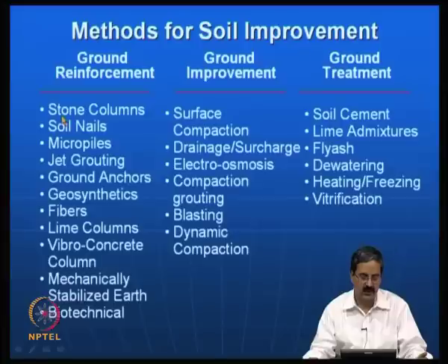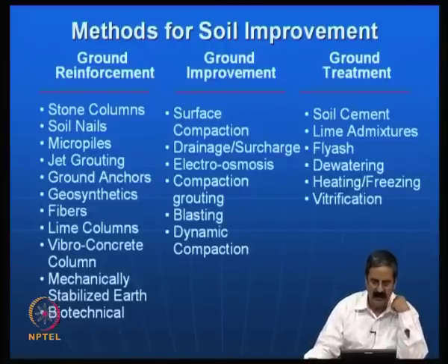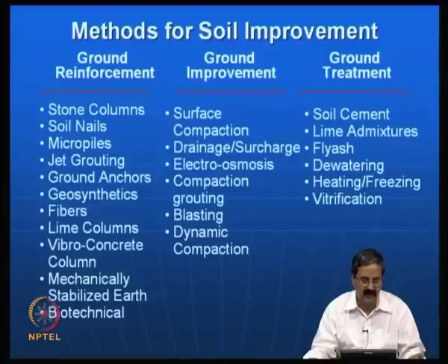Say, for example, stone columns are a technique used in the case of soft soils. In many of the coastal areas in India, whether it is Vizag port, Kandla port or Cochin port, you use stone columns. In soft soil, the load is so much that it cannot be taken care of, but similar to piles, stone columns made of a matrix of stones and aggregates will take the load. So, it is a sort of reinforcing the ground, and that is the reason we call it reinforcement.